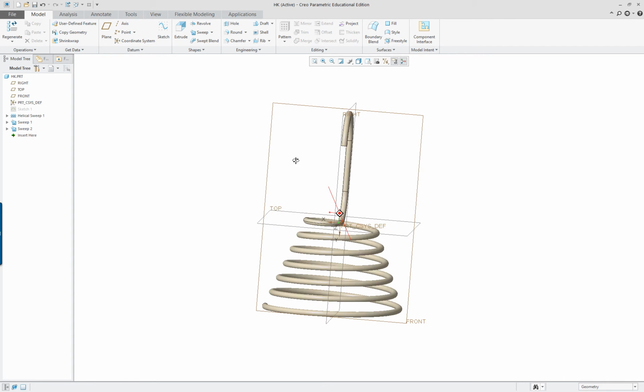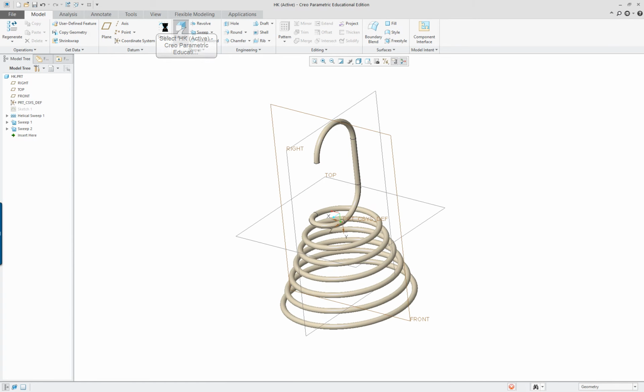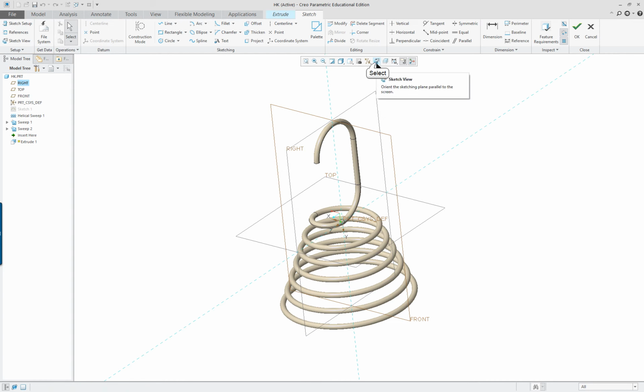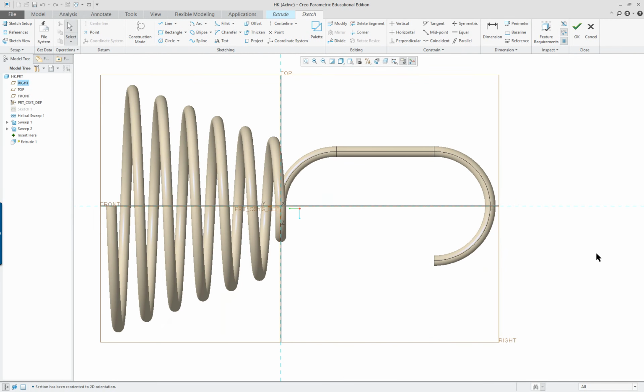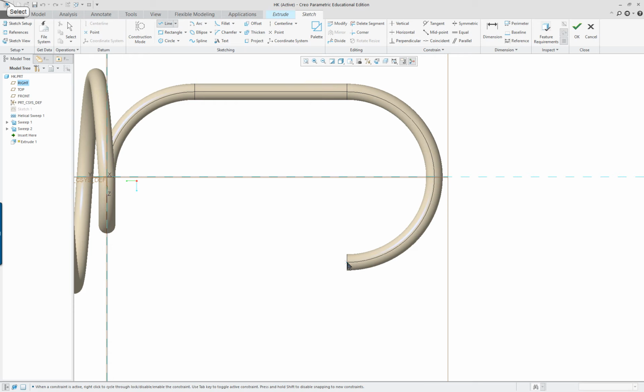All right, so the other thing on this here is putting in a little cut and extrude, remove material. I'm going to select this as my sketching plane, sketch, and I'm going to just put one line in from here at an angle. I'm not sure, I think the angle was 60 degrees. We can leave it like this for now. And I'll do 60, see what happens. Do 30 and see what happens. No, too much. I want it to go down in here.